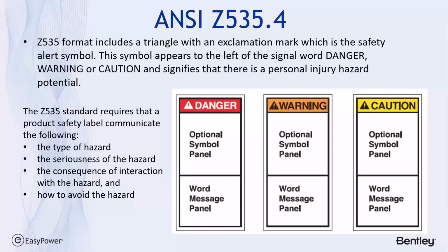And so if you have incident energy calculations at 40 calories or even 20 calories, that could be a situation where, if you didn't have on the proper PPE, you could be adversely affected. So I'll leave that discussion to the committee. The movement is to have everything have a warning label and make sure people are trained to understand how to equate the warning label to the need to wear a certain level of PPE.